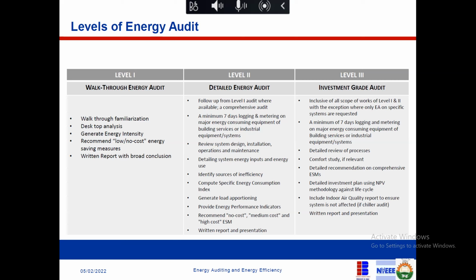That's why in some big organizations, the facility manager will set the AC at 24 degrees automatically. Some people, when it's at 18, will still open a window, but that is consuming energy. It's not like when you turn on your AC it consumes a fixed base energy. No, depending on the temperature, that's what you consume.